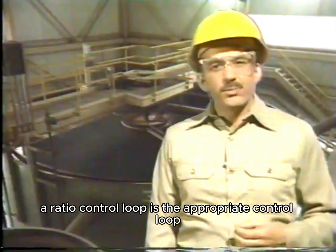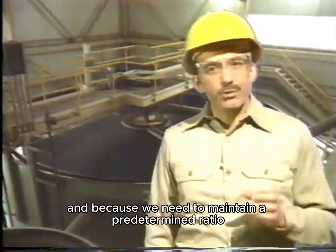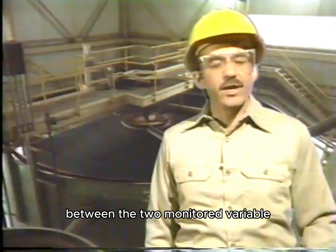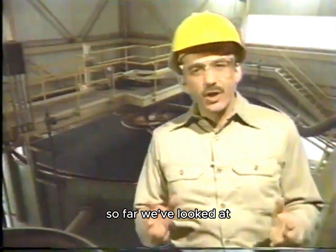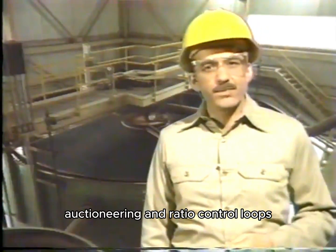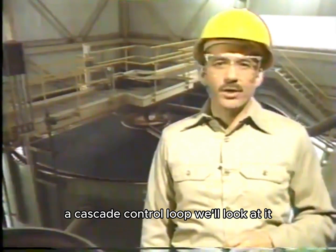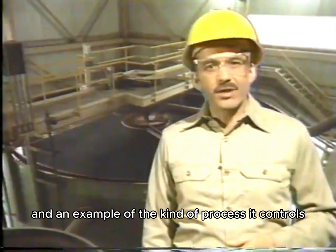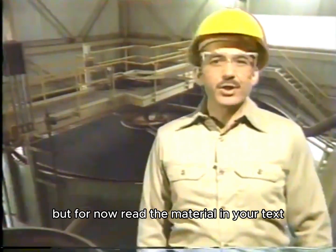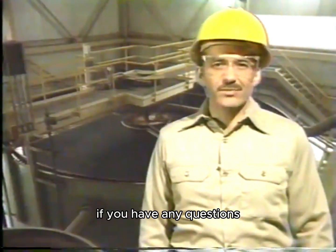A ratio control loop is the appropriate control loop for this process. Appropriate because we need to monitor more than one variable, and because we need to maintain a predetermined ratio between the two monitored variables. So far we've looked at two kinds of multi-element control loops, auctioneering and ratio control loops. A third multi-element control loop is called a cascade control loop. We'll look at it and an example of the kind of process it controls in the next part of this program. But for now, read the material in your text and answer the questions that follow. Be sure to check with your instructor if you have any questions.